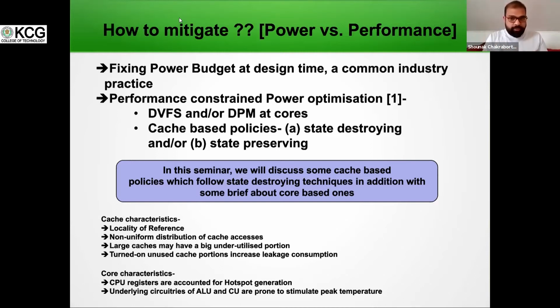You just reduce the voltage of a particular domain of the cache, and your data will be there as it is. To preserve the state of the data, you just reduce your voltage up to a certain level. That is actually achieved by using some multi-threshold CMOS circuitry on chip. However, in this seminar, I'm not going into the details of the circuit technologies.